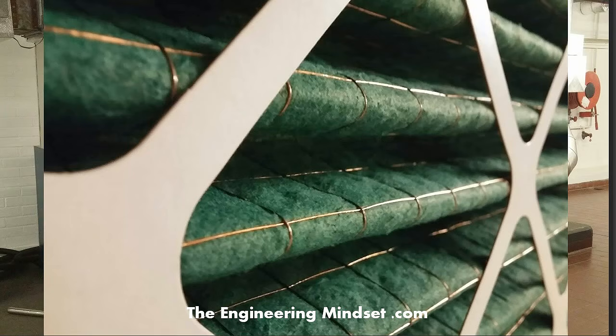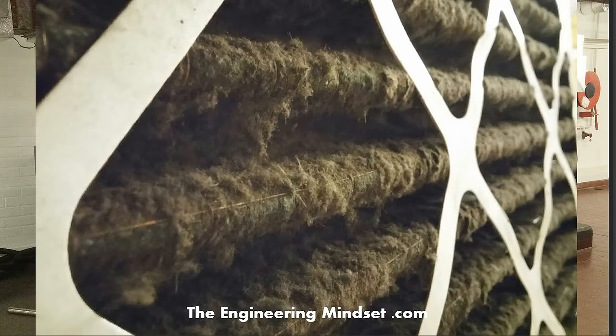Looks quite nice. And then a few months later, after maybe a few days, it depends where your building is. If it's sucking air off of the motorway, next to an industrial site, maybe near a coal power station or something, you're going to be going through a lot of filters. So this is what the dirty filter looks like, only after a few weeks, a few months. It depends where you are, like I said. And you can see, look at the amount of dirt here.